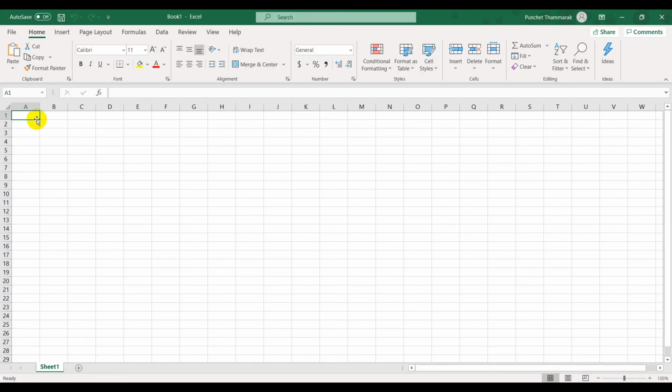Let's play with the T cross section. So the top of the T, we will discretize the top part using a small mesh size, and the bottom part, how to say, the part below the neutral axis approximately. Okay, this part here should be under tension, and it will contribute nothing to the force resistance. So less discretization at the bottom part. Okay, so let's do this.